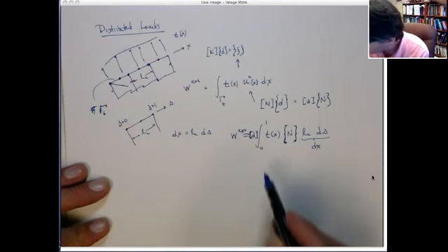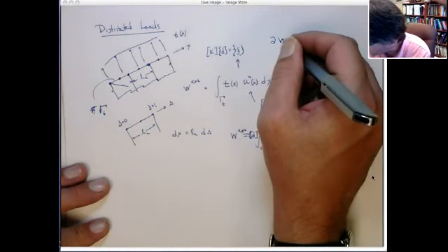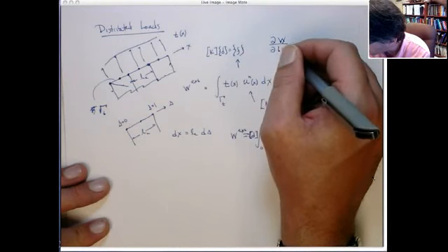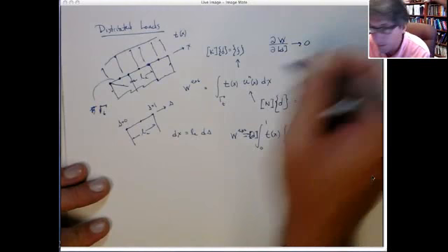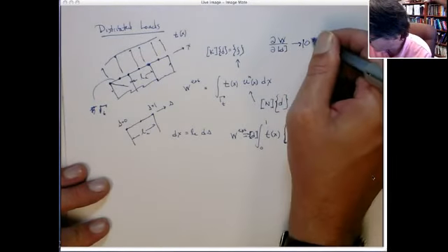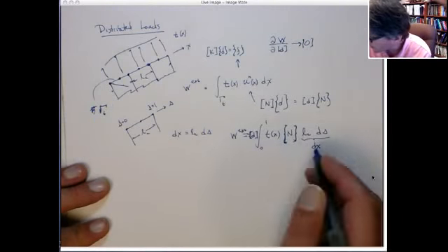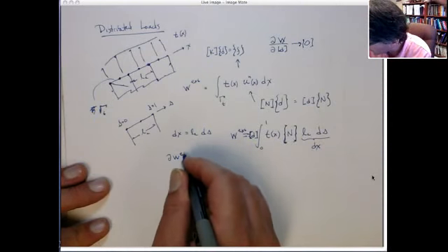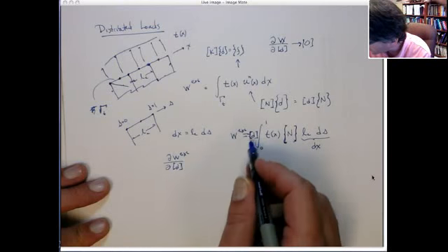All right. Now, when we got these equations, we got this by taking the derivative of the total energy, or the total work, with respect to the nodal unknowns. And we wanted to minimize that and set that equal to 0. It's a vector. Okay? And that's how we arrived at these equations. So let's look at when we take the derivative of this with respect to d. Well, when you take the derivative of the external work with respect to the nodal values, you can see they just show up here.